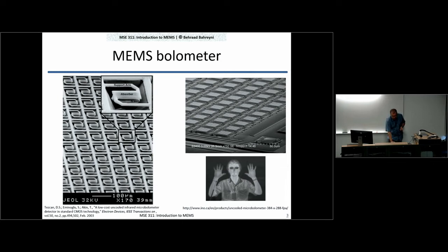You see that the sensor itself is hanging in a small cavity that we produced here through, guess what? An isotropic etching of the substrate. That's one part, that it is hanging in a cavity, it's not touching the substrate. And the second part is that I could have directly connected it to the substrate with 2 short arms here, but I'm not doing that. It's going through a long arm attached to this end and another long arm attached to this end. So that's one design feature you can notice here immediately.